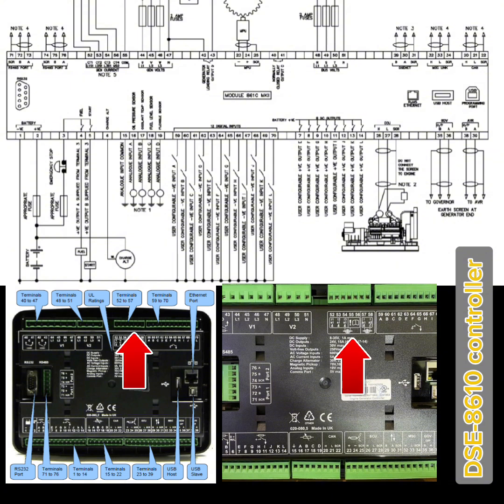And next are the CT points, you will connect your CTs at 52, 53, 54 and 55, 56, 57 and 58. These are all CT points. Numbers 52, 53 and 54 are red, yellow and blue, you will connect your red, yellow and blue wires for the CTs. And the next point is the common, where you connect all your CT S2 points.